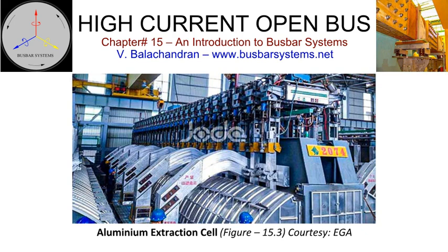Such high DC currents are associated with a large unidirectional magnetic field. The magnetic field produced by DC will not induce eddy current or hysteresis losses in neighboring metallic objects. As stated elsewhere, the ripple contents in the DC, if significant, can be a cause of concern.